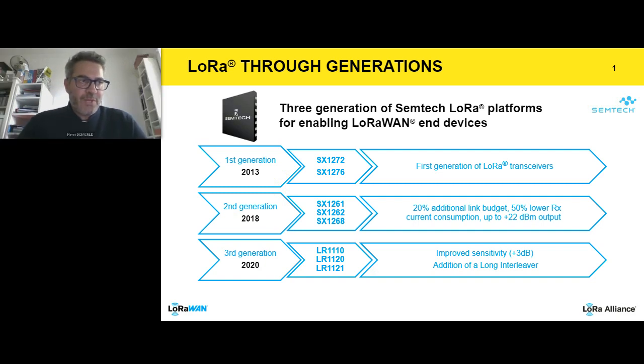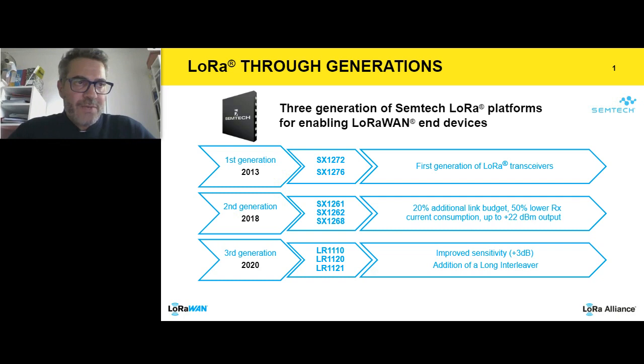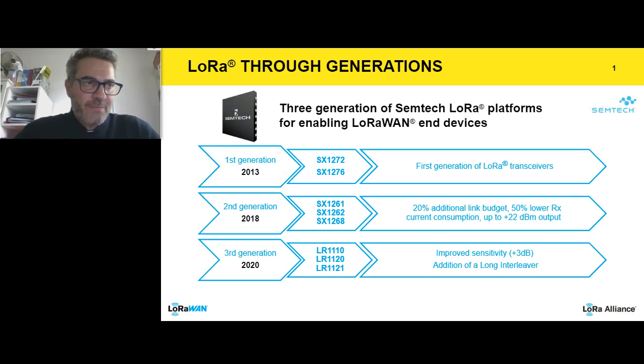The different products are designed to cover the different regions again, but they also include support of LR-FHSS, which provides additional data rates available in LoRaWAN. They are all suitable for Europe with ETSI, North America with FCC, China, Japan, Brazil, and so on. Also, this second generation supports the fastest spreading factor using a bit rate of 62.5 kilobits per second.